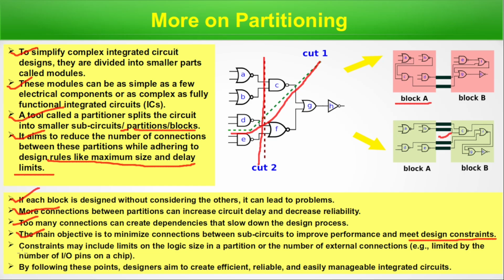That is the main objective. So constraints may include a limit on logic size in a partition, or the number of external connections, which is limited by the number of I/O pins on a chip. Now, by following these points, designers aim to create efficient, reliable, and easily manageable integrated circuits. A designer has to follow all these constraints.